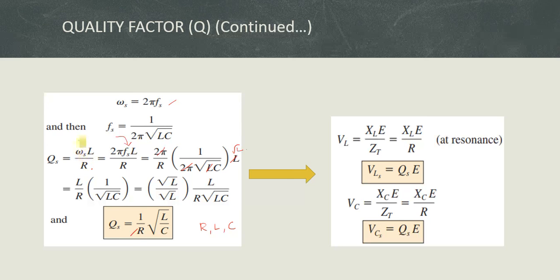If I want to find out the omega value, definitely I need to know my resonant frequency to find out the value of the quality factor. But in this formula I need only the elements of RLC in order to find out the quality factor. So depending upon the problem specified, we use any one of the formulas to find out the quality factor of the corresponding coil.